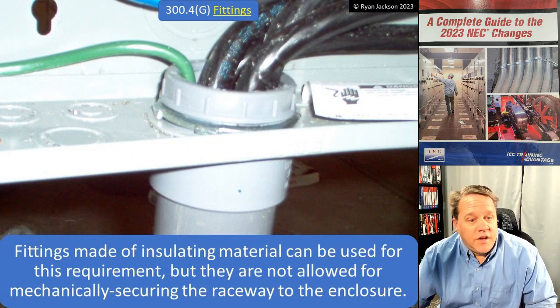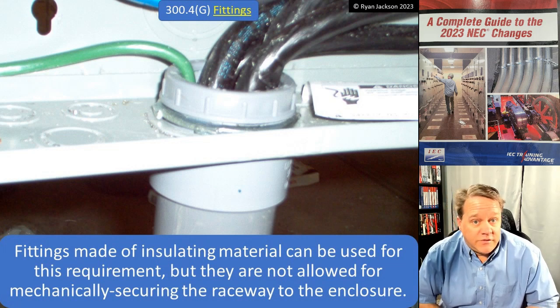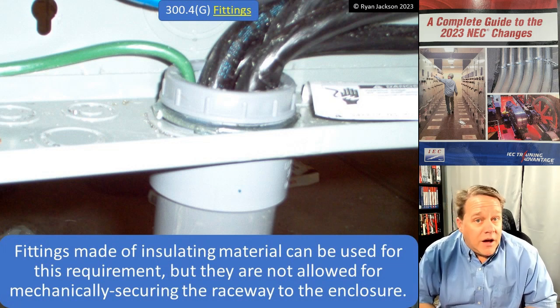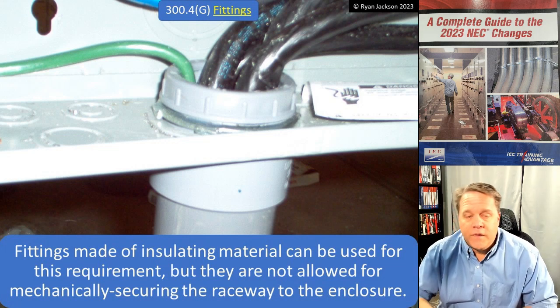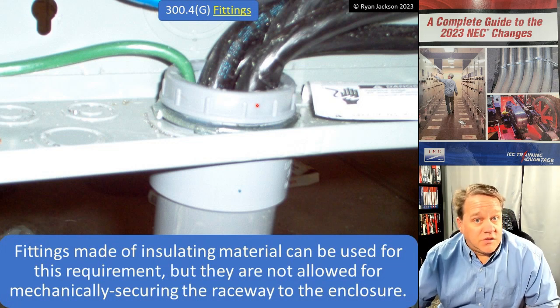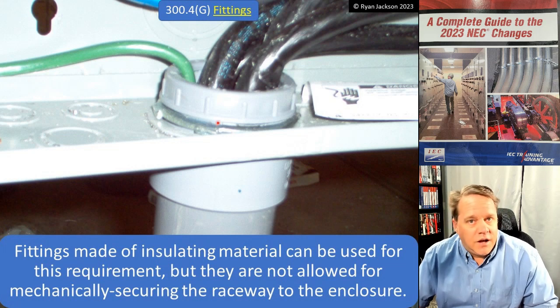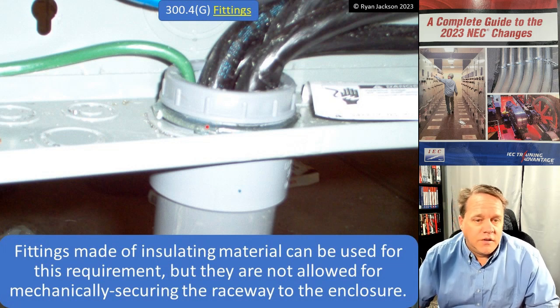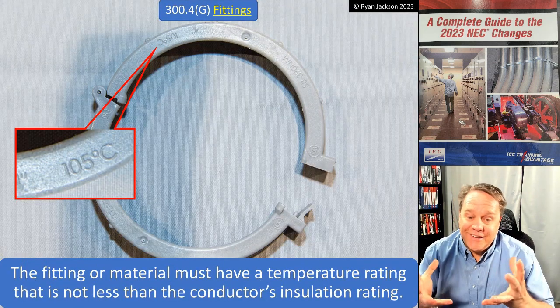It goes on to say that fittings made of insulating material can be used to satisfy this requirement, but they're not allowed for mechanically securing the raceway to the enclosure. All right, so yes, you can use a plastic bushing to satisfy the protection requirement, but you still have to have a lock nut. That's all this rule is trying to say, which makes a lot of sense in my opinion. The last sentence in this section is kind of funny.